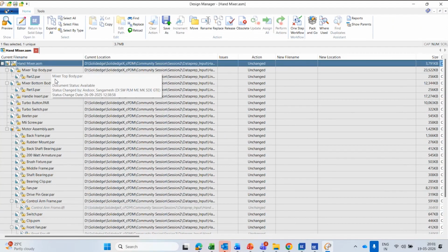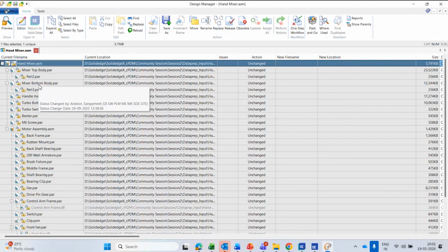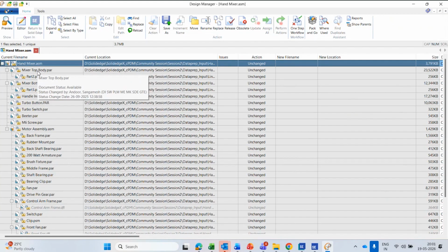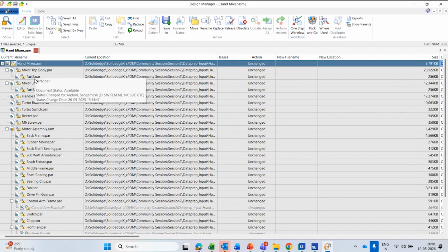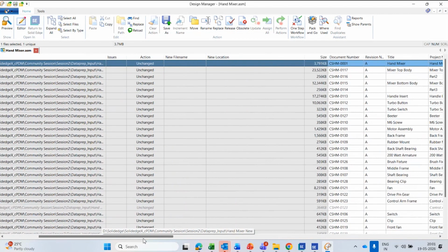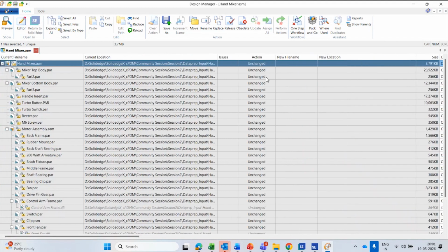So for the top level assembly, including all, these are the file names which you will see even on upload, under the Solid Edge dataset type. But in case you want to match these names to the item IDs, so the dataset name is the same as this document number, in that case you can perform this step, that is the save as file name step. Otherwise, once the data prep is done, you can go ahead with the upload action.